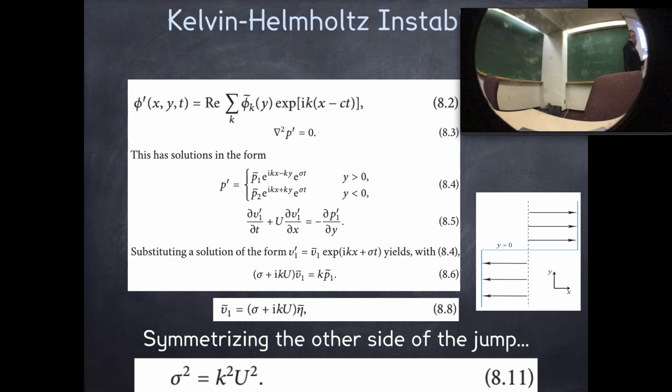So in the linear instability terminology, we are seeking a non-trivial solution to this kind of homogeneous differential equation. It's homogeneous because everything in this equation depends on one of the flow variables. I always have the trivial solution in a homogeneous system of setting them all to 0. I don't want to do that because I'm actually solving for something that's non-zero.